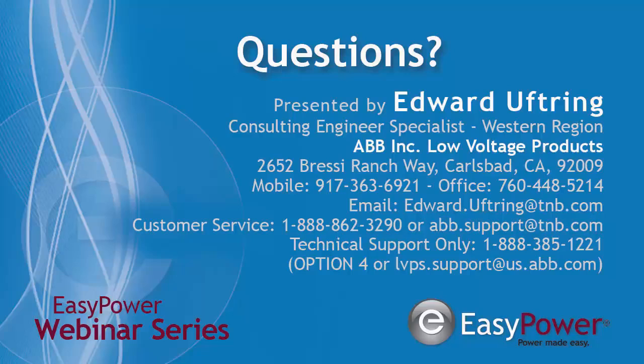What they are using is actually optic feedback. So we're looking for the flash of light because it's the quickest. The speed of light is as quick as we can go. And using optics and fiber optics back to a unit, that's how quickly we can open ours, extinguishing the arc as quick as possible. Again, another presentation.